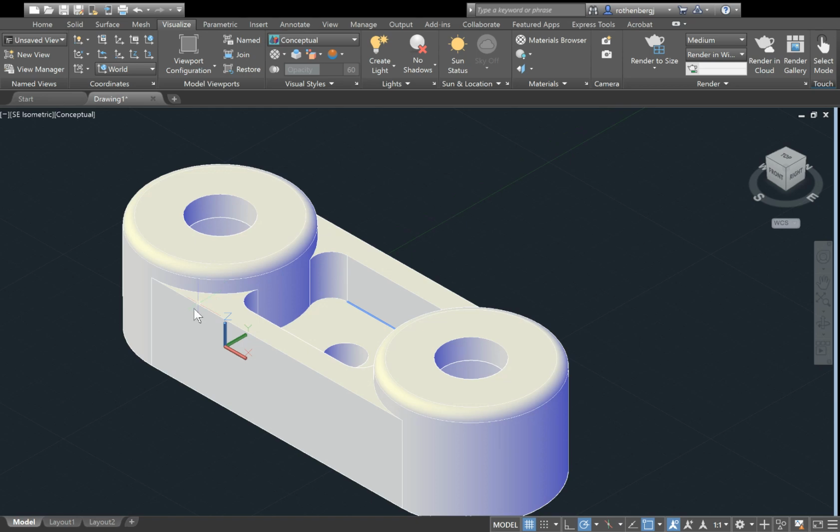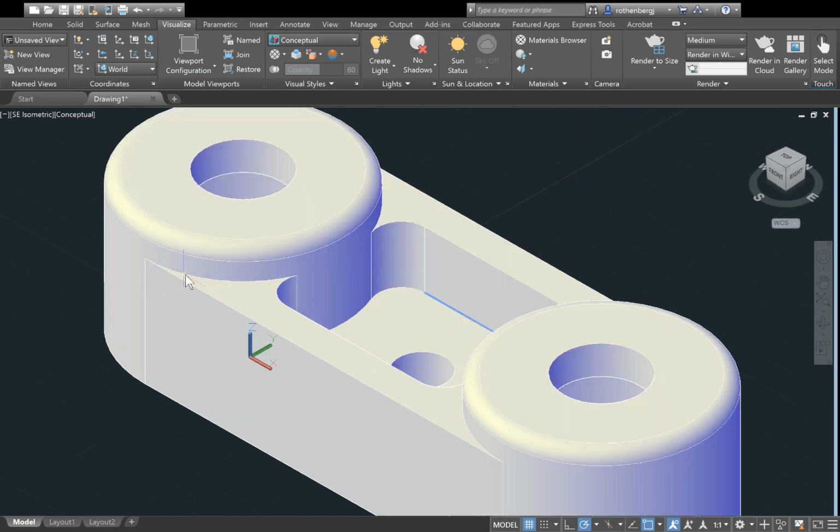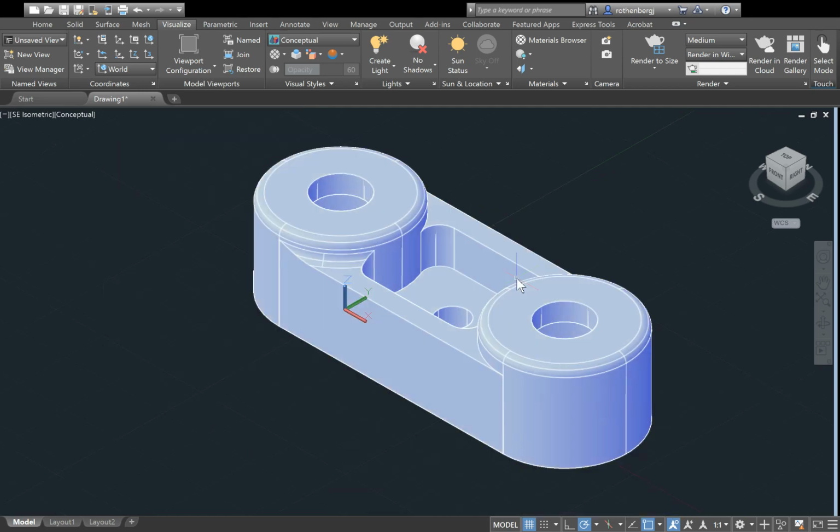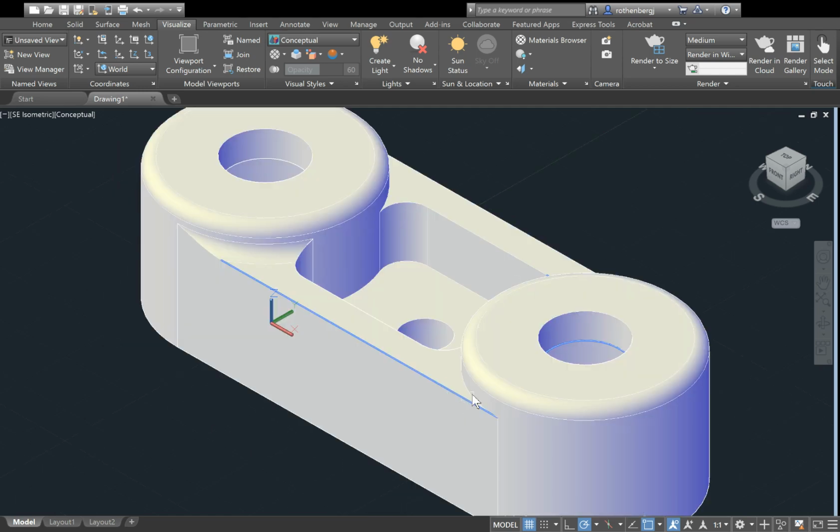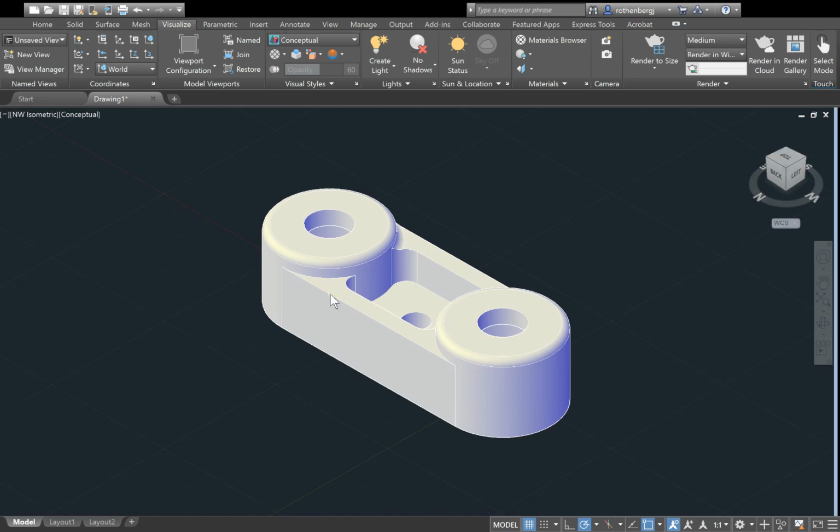So now we are going to be doing it on the edge where the rectangular-ish piece intersects with the cylinder. So we'll be using fillet. Select that edge. It should still be 1/8. Again, change it if you need to. Hit enter again. That's good. Do the same thing on the 3 other corners where they intersect. Change your view as you need to.